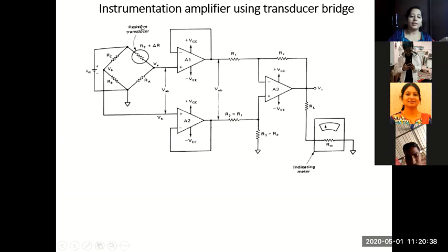So it is called a resistive transducer, and basically it is a thermistor. So how do I indicate the value of a thermistor? RT base value plus or minus delta R, because it's going to change in resistance. And you can see this bridge is excited by a DC voltage VDC between these 2 points, and the output should be measured between the opposite 2 points. If I excite the bridge between here and here, say I call this, for example, C and this D.